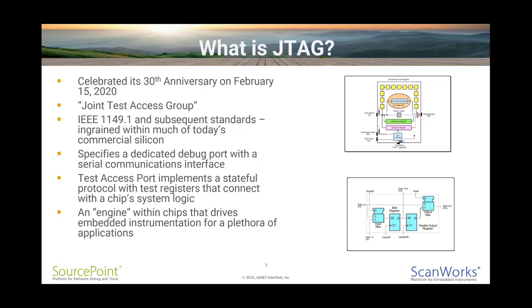It has a very simple architecture: a finite state machine, as in the top diagram on the right, drives the actual control. Behind most pins there is a couple of handfuls of gates, which constitute a boundary scan cell, which allows serial access around the perimeter of the device, and parallel data in, data out access through the pins. The boundary scan cells and JTAG mediate between the outside world and the system logic inside of the chips.